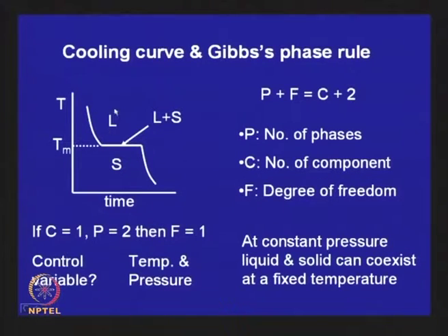you can say that atoms are arranged in a disordered fashion, but there may be some amount of short range ordering. Using X-ray diffraction technique, the density of packing also has been estimated. In case of solid, we have seen that the maximum coordination number in metal that you can have is 12 in face centered cubic, whereas the same metal, which has a face centered cubic structure in solid, if it gets converted to liquid, possibly you will not have 12 as the coordination number. Coordination number will be less than 12, but nevertheless still quite high, maybe 10, 11.